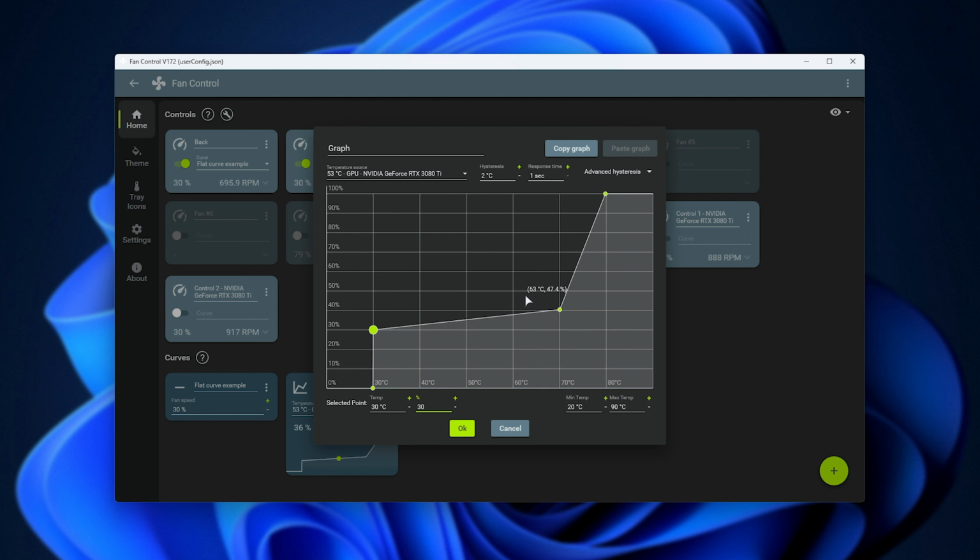On top of this, to make a drastic jump, for example, such as this one over here, from 30 degrees at 30% to anything below this at 0, we can add a second dot, and you'll see that it's at 29.9. To make a pretty much straight line, just make sure that the number is about 0.1 less. Anyways, super advanced. Mainly, for the most part, you'll find out where your fans are noisy and adjust this to be some kind of smooth curve or gradient like this.